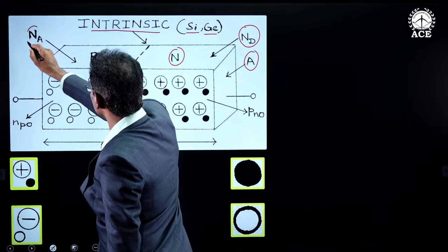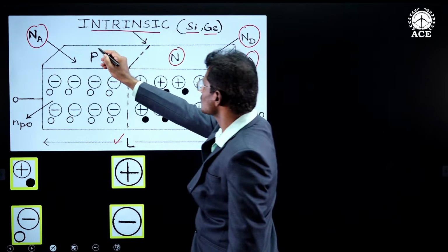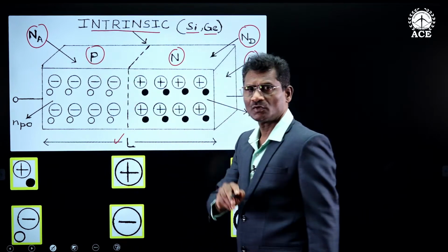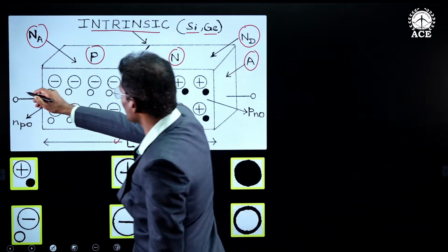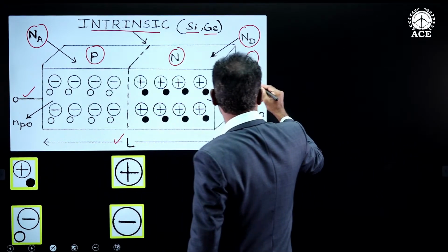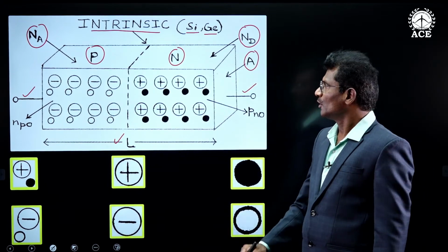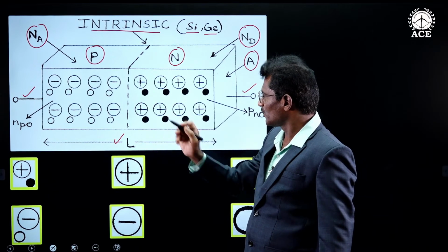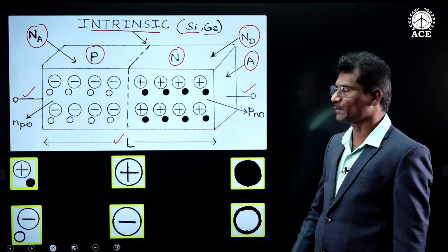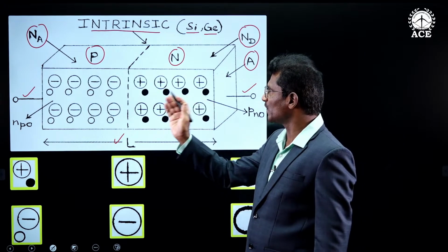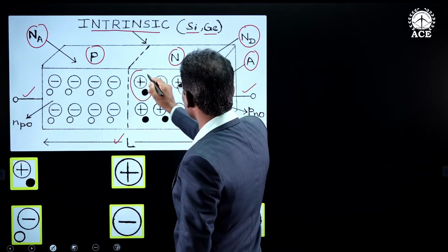At the other side, acceptor impurities are added, making it P-type. Acceptor means trivalent atoms. Later on, from either ends, two metallic contacts are pulled out. This central dotted line is an imaginary line which is drawn for explanation purpose, just to separate the P and N sides.